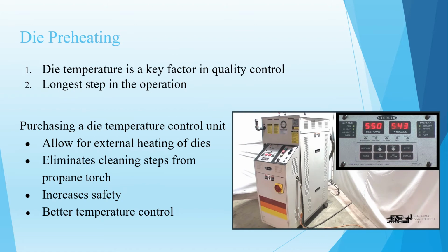Die temperature is a key factor in quality control, but it's also the longest step in the operation. An external die heater will allow the heating of dies to become an external process, and in the process, increase safety by eliminating the use of an open flame and eliminate the cleaning of dies associated with the use of a propane torch.